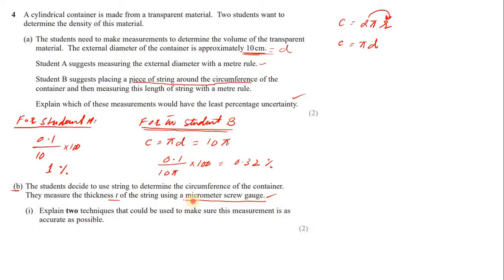Generally, with a micrometer screw gauge, two things are there. We have to take care of the zero error. Generally there will always be some zero error if the instrument is not new. If it is used frequently, then there will always be a zero error because this is a quite sensitive instrument. So we take care of the zero error to find the correct reading.